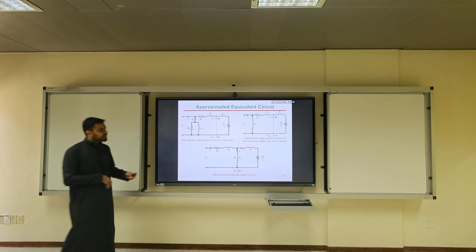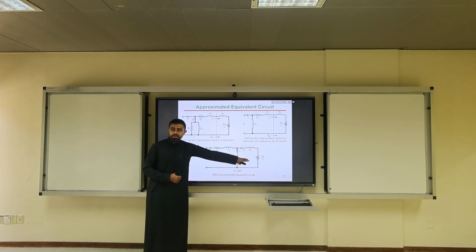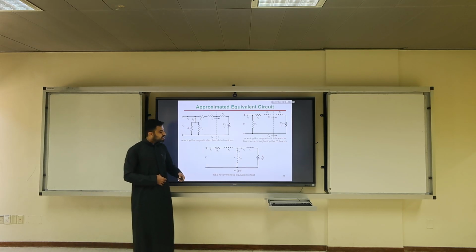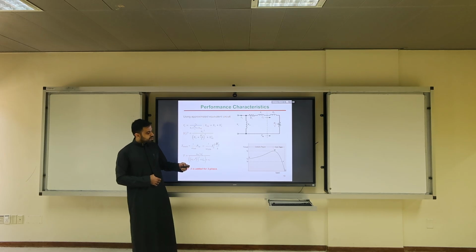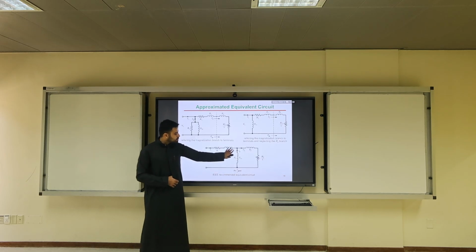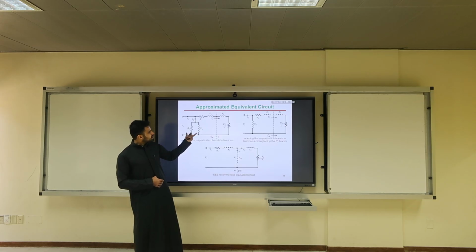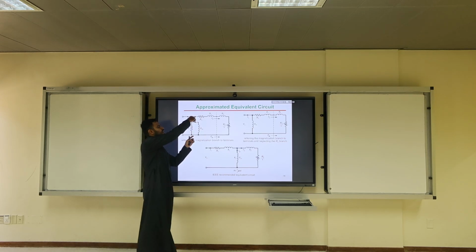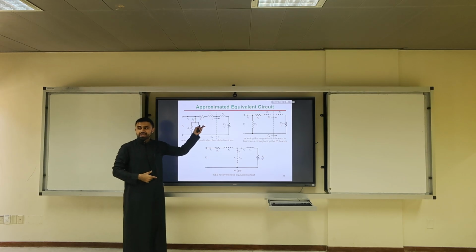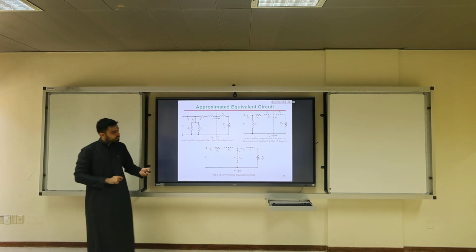For the equivalent circuits, I told you I like this circuit the most. The second circuit that I like is the one where you move the branch here. This circuit is also useful where you put R1 here and the parallel branch here, because you will have I1 to be I parallel plus I2 prime, and we will solve an example using this circuit.